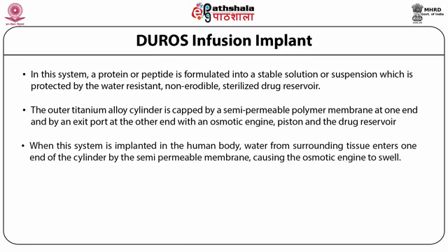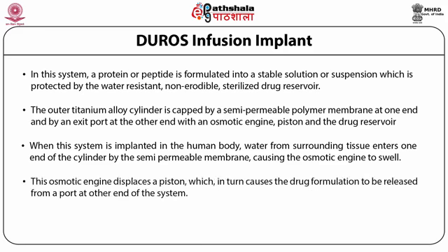When this system is implanted in the human body, water from surrounding tissue enters one end of the cylinder by the semi-permeable membrane, causing the osmotic engine to swell. This osmotic engine displaces a piston, which in turn causes the drug formulation to be released from a port at the other end of the system.